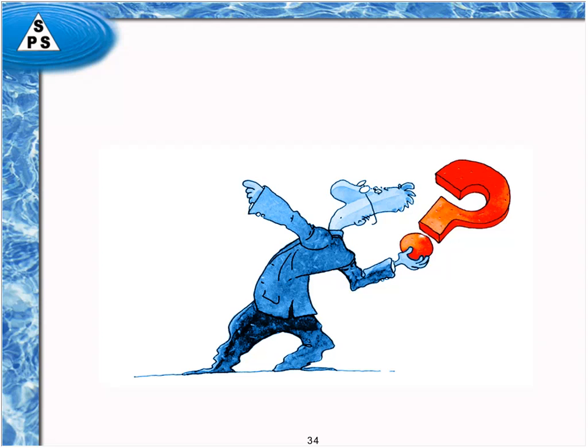My strong preference for anything is going to be heat. If you can do it with heat, that's your best choice, because, like I mentioned, it doesn't take much heat to kill organisms, and it does penetrate, although it does not remove the dead biofilm. And the second choice after heat, before you get to the other chemical sanitizers, would be ozone, because ozone can pretty much be used continuously. So that's, in a nutshell, my opinion on sanitizers.